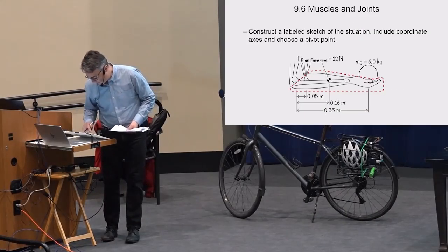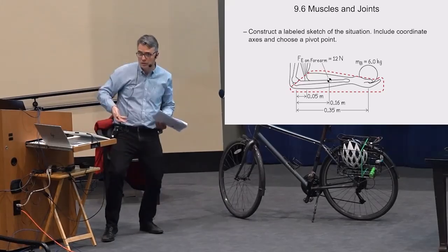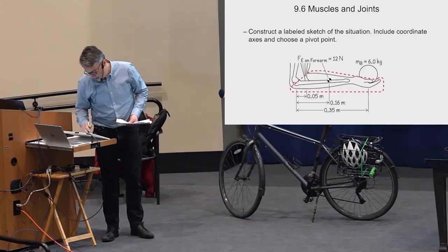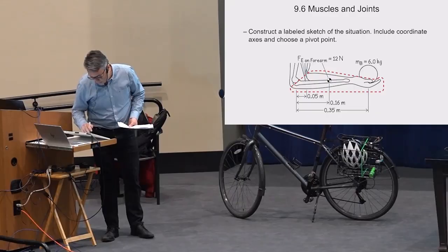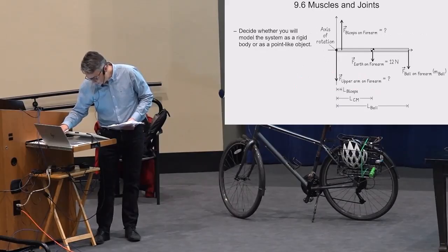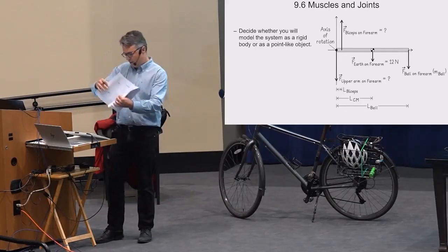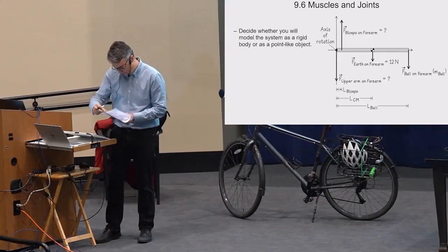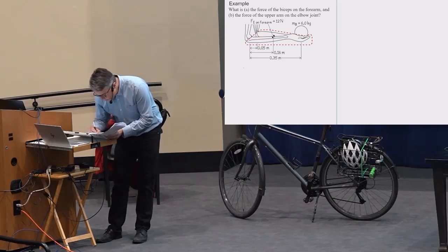for the forearm there. And think of the weight of the ball as being an external force pushing down, the weight of the forearm itself as being an external force, and then there's some force upward from the bicep and another different force on the pivot itself. Okay, so this is kind of the extended free body diagram. Some of these are a little weird here, but let me see if I can solve it on this part right here. So what I'll do is draw this.